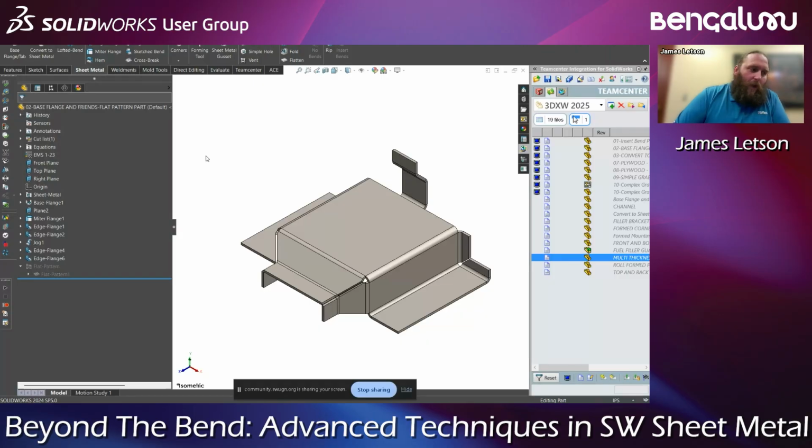But it's a bit of a science, and it's a bit of, I'm not going to say guessing. It's not quite guessing. It's educated guessing, right? That's the best way to put it. Sheet metal definitely has a bit of a tolerance. And it also depends on your sheet metal provider, like where you get your sheet metal from. That will determine how the metal bends, right? Certain suppliers' metal bends differently than others.